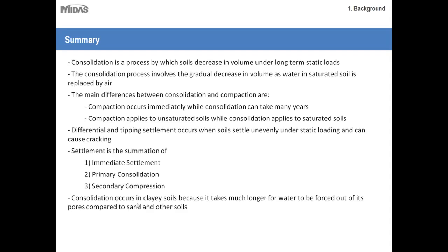Consolidation occurs in clay soils because it takes much longer for water to be forced out of its pores compared to sand and other soils. That's the main characteristic to keep in mind about clays: when it's saturated, the water takes a long time to be pressed out, and that's why settlement takes so long.